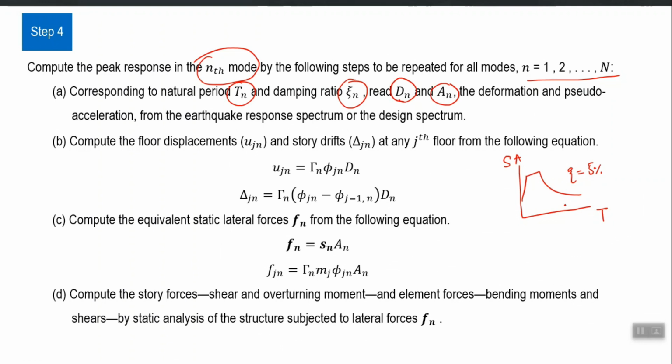I think if I am not wrong, up till ASCE 7-05, the equation for the spectrum was a function of damping ratio also, right. So for 5% it reduced to almost the same equation, but for any other damping there was a modification and then you plot for that damping.